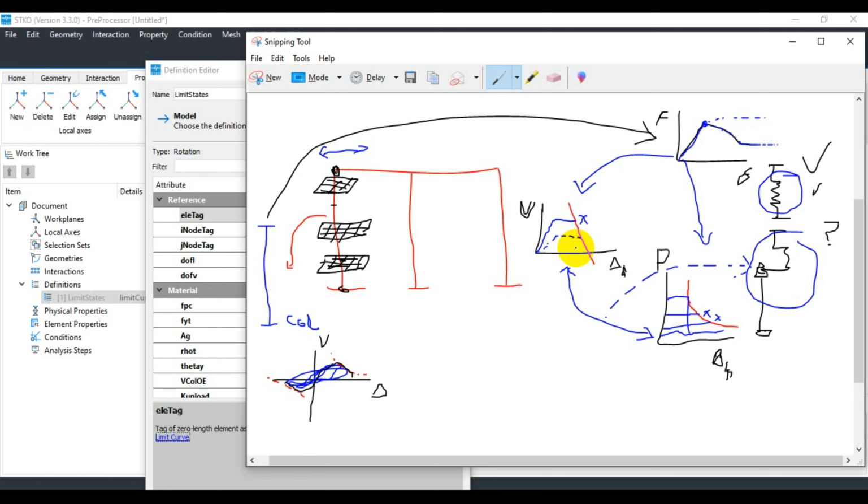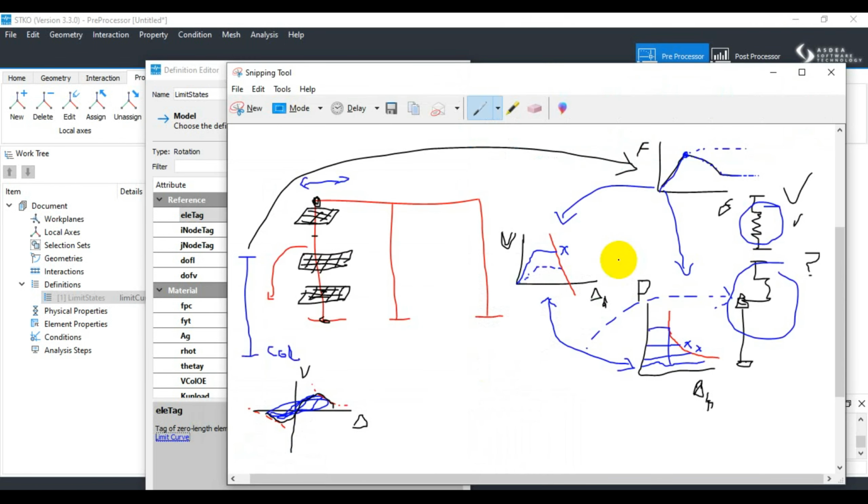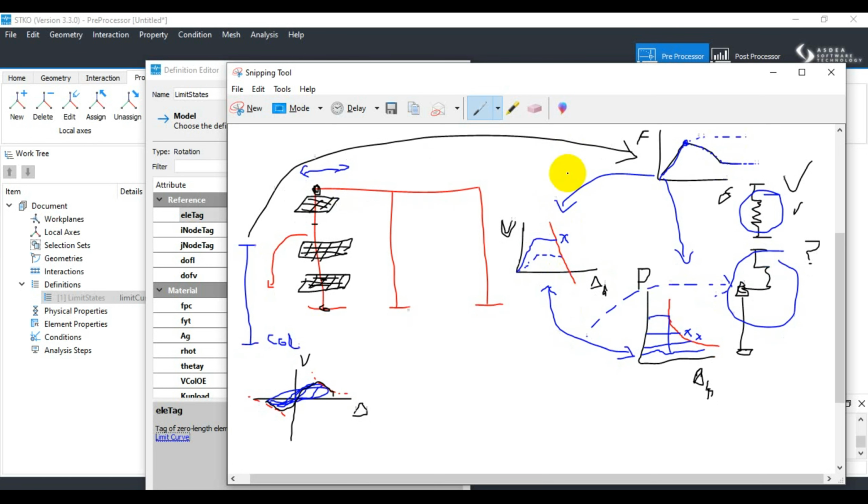Depending on the application, the material model could define the relationship between stress and strain, force and displacement, moment and curvature, moment and rotation, etc. It depends on the available experimental work that is performed in OpenSees, and this is the most simplified model in the OpenSees environment. It is the lowest level of object that composes elements in OpenSees, and one-dimensional elements such as springs and truss members require only one uniaxial material model to define their response.